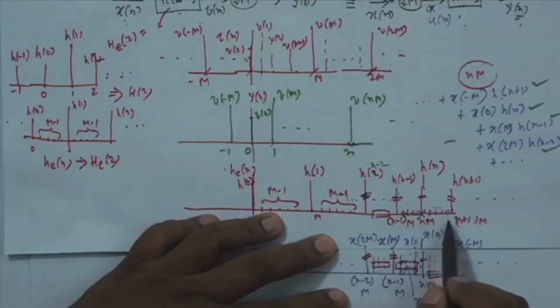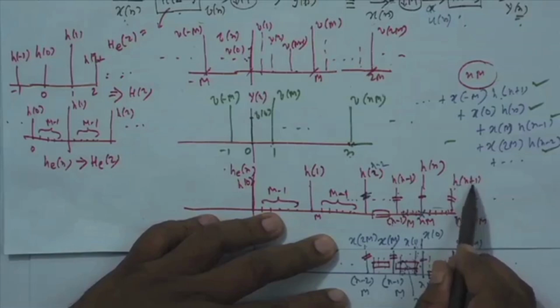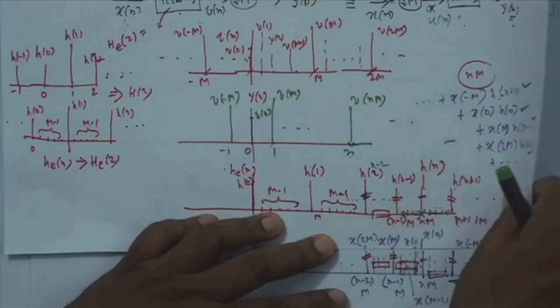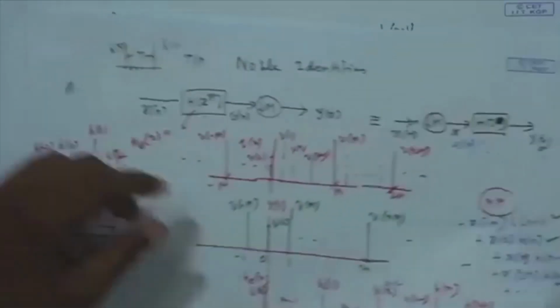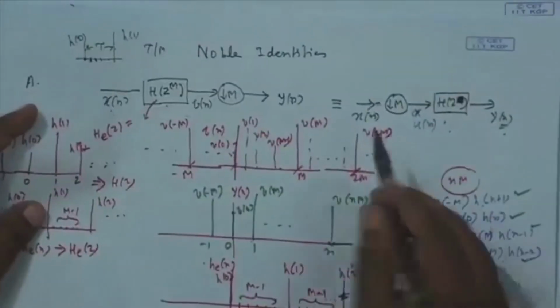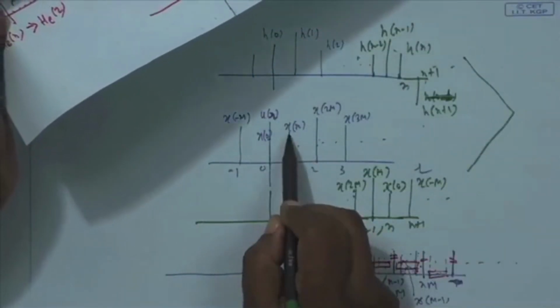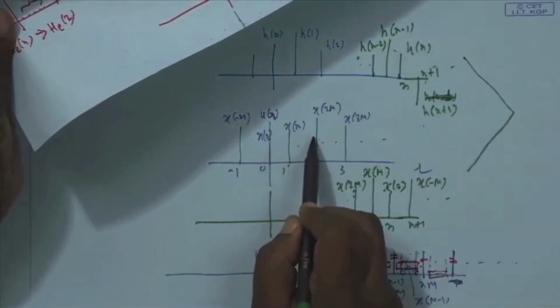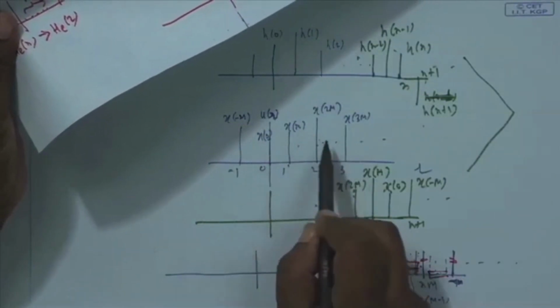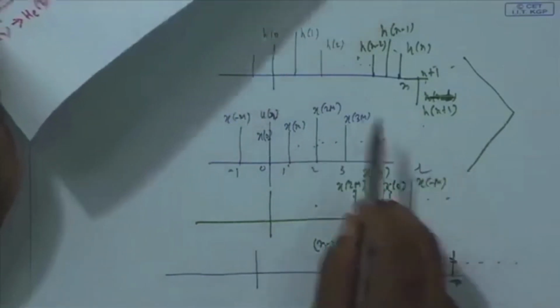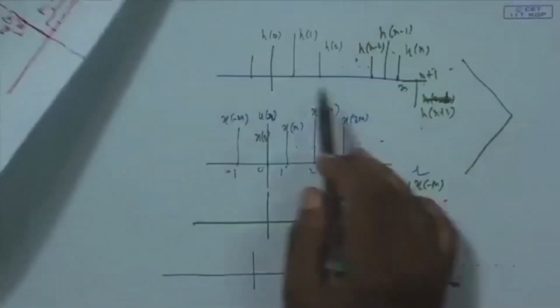So, that is what I got, and I showed this is equivalent to this, because if you decimate x n by m, the sequence you get is x 0, then the first sample is x m, not x 1, then the second sample is x 2 m, because you are throwing out the intermediate m minus 1 samples, then the third sample is 3 m dot dot dot, and this is your h z, meaning the original h sequence.